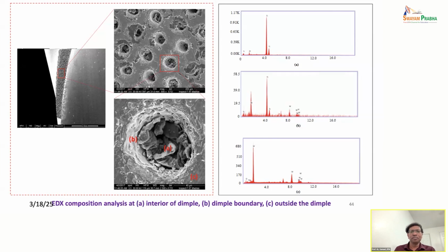But sometimes they also get welded, so it becomes a challenge. We cannot have infinite life for these things. Even on a plain surface, when you make the dimples and they get worn out beyond their lifetime, they will be gone. You might have given a particular depth, but after it gets worn out, that depth decreases.